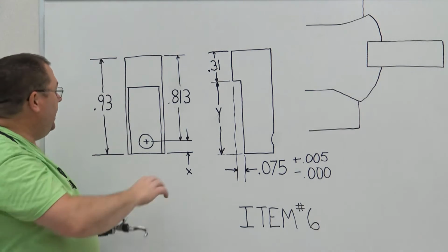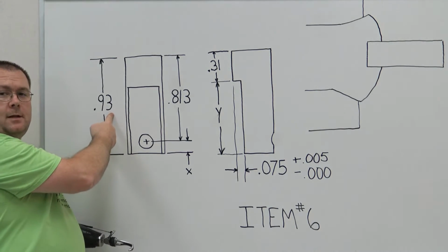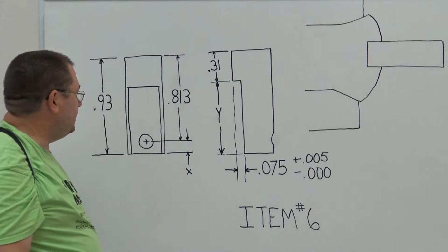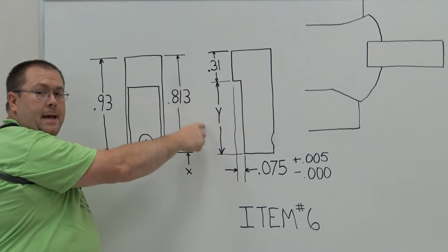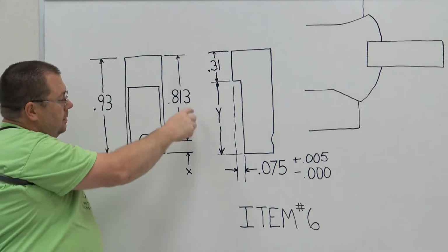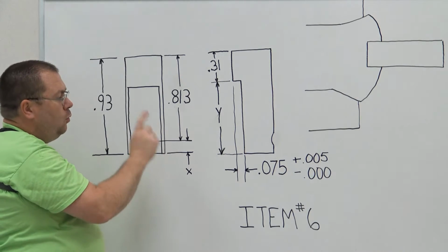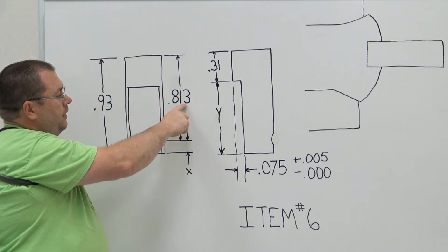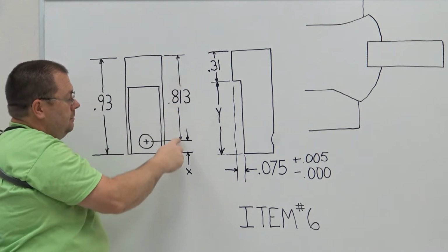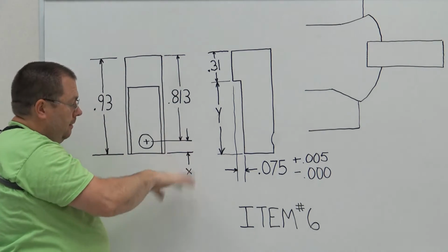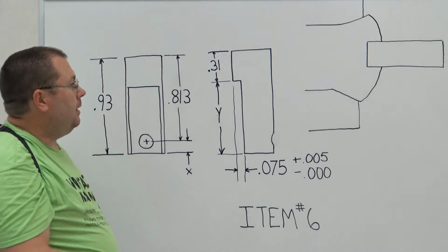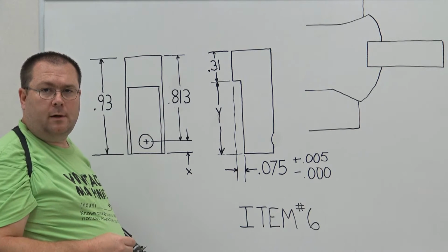Now 939 on a caliper reading, is it still a good part? Absolutely, it's within the plus or minus 10 thousandths tolerance. But if I did the math as though everything were perfect, exactly the dimensions, then this dimension would in no way allow this 813, which is the critical dimension, top of the piston to center of the pin. Everything down here doesn't matter. Where it does matter is how we're going to do the machine work.